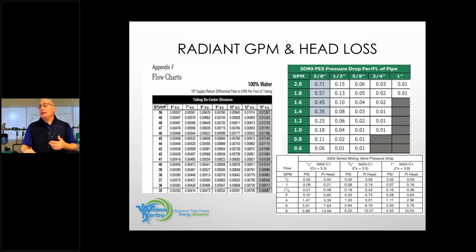One other thing to take into account, you see another chart I have on here, which is the mixing valve. I'm going to have to use a mix valve. Now, you've got condensing boilers out there where you can program in multiple temperatures. Just understand, it still can only make one temperature at a time. So for this zone, since it's one room and it's a kitchen and they're going to be cooking, right? And if they're Italians like we are, they're going to be cooking a lot. So maybe that would be okay. But if it was something more substantial, you probably want to do a mix valve on there.